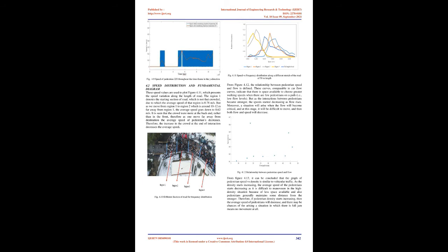Then, we also selected the wall. There will be a force on the subject pedestrian from the nearest point of a wall, which is repulsive in nature. Then the sum of all the forces on the subject pedestrian is taken, and based on the force, the future velocity is calculated. The above procedure is repeated at a time frame of 80 milliseconds. Afterwards, the parameters which were selected for calibration are obtained through the genetic algorithm, in which the difference between actual and simulated position is minimized. The above figure represents the subject pedestrian, the blue one, which is going to be simulated with the help of the above model applied.